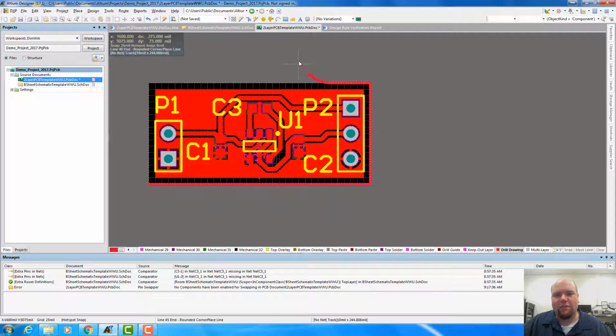So in this case we're doing 45-degree sweep, straight 90 degrees, 90-degree sweeps, just straight angle, whatever it is, and then we're back to our 45. So if we want to go back to straight, or if we want to go back to 45 and then straight, we hit the space bar again. So again, it was Shift plus space bar to move styles, and space bar to flip which axis gets corrected first. And then hit escape.